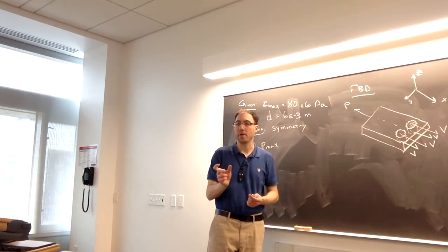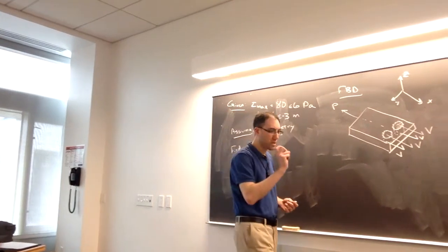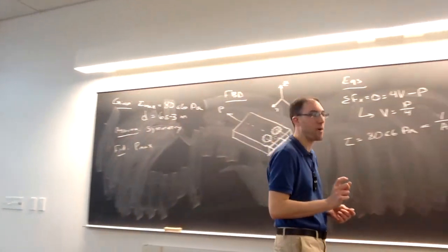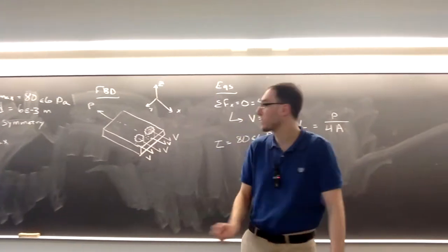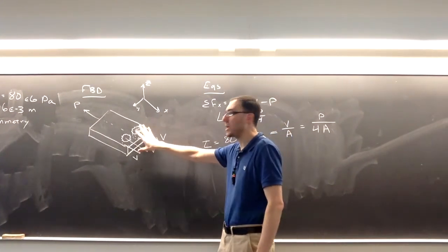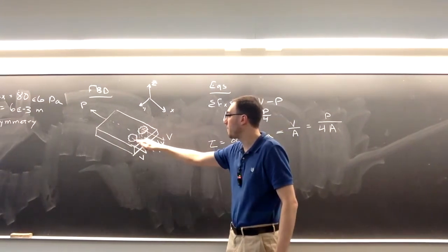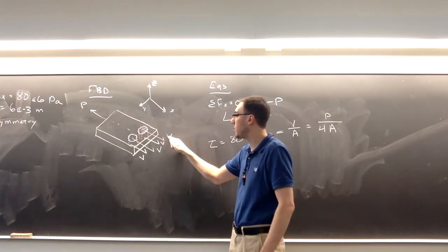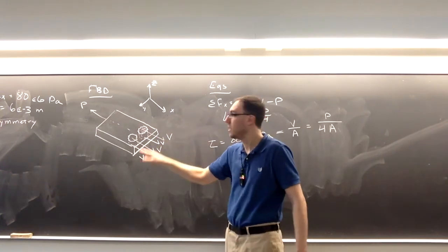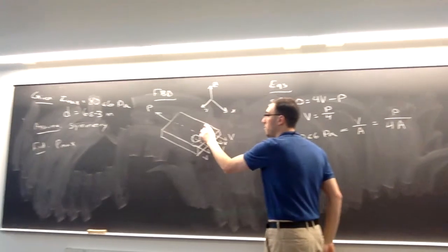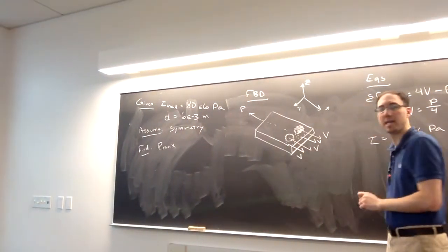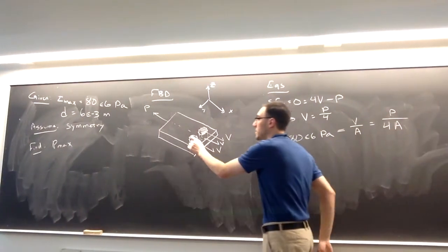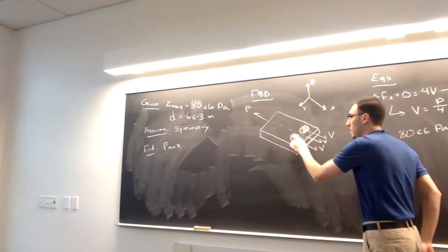Right, it's the cross-sectional area, and this is where we have to be cautious because there are different ways we could represent this, like we saw last Thursday. The way that I drew this, I put for each surface its own internal shear force V, meaning that this V is only acting on this cross-sectional area. This V is only acting on this cross-sectional area.